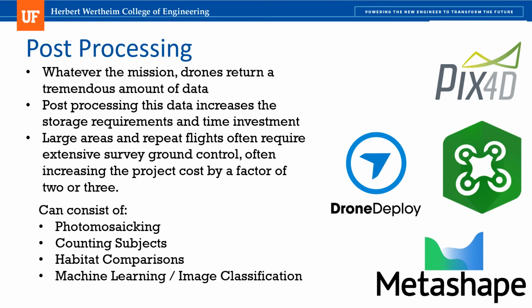Whatever the mission objective, drones capture tremendous amounts of data which require storage and post-processing. Post-processing the data increases the storage and time requirements for a particular project, and large area or repeat flights require extensive ground control surveys which tend to increase the project cost by a factor of 2 or 3. Post-processing can consist of photomosaicing, manually counting subjects, habitat comparison, and machine learning image recognition scripts.